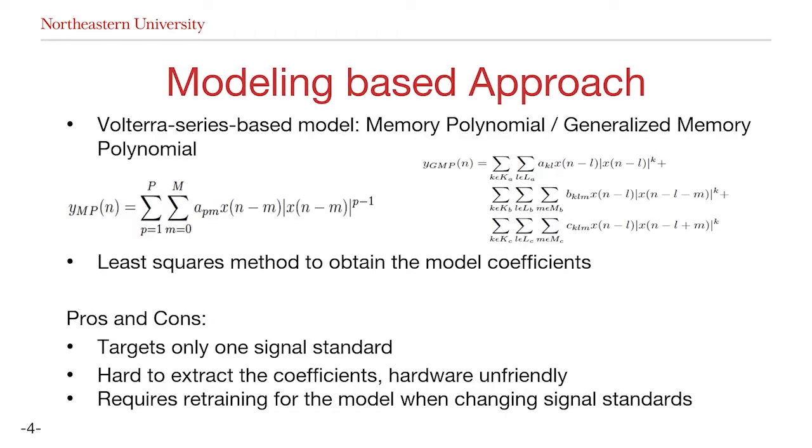One of the traditional ways of building the DPD system is to use the behavior modeling method to describe the PAs and then apply the reverse model to the input signals. Among these models, the Volterra series-based models are the most studied and used. The Volterra series is generally used to describe nonlinear systems as it has the ability to capture the nonlinearity and the memory effects of the system.